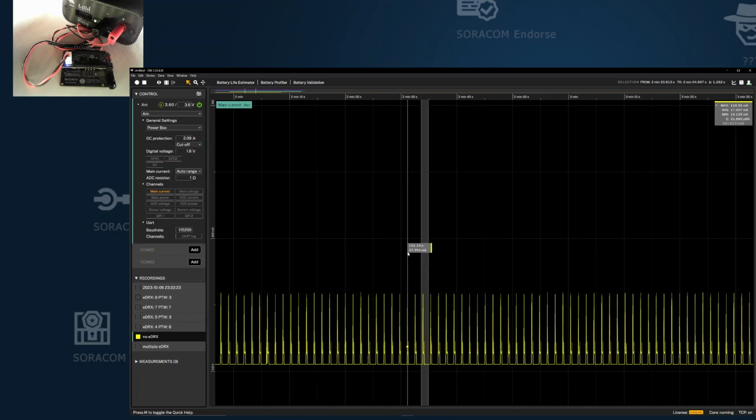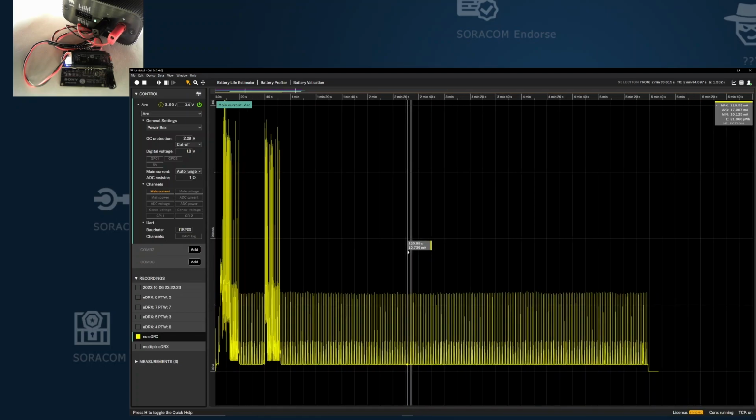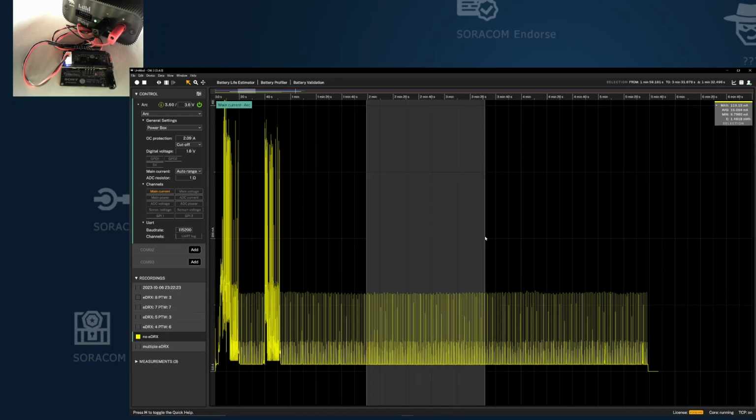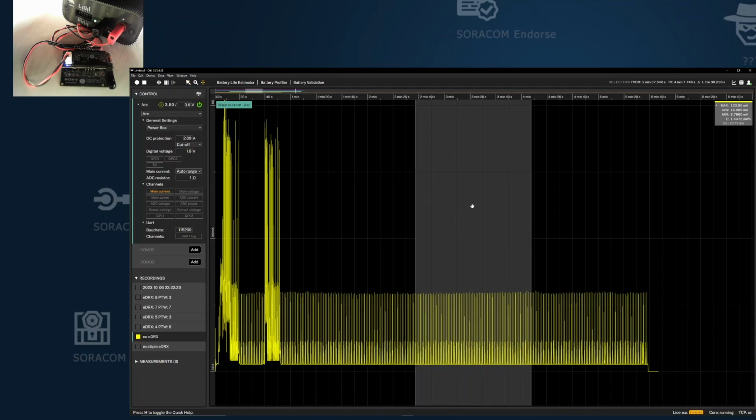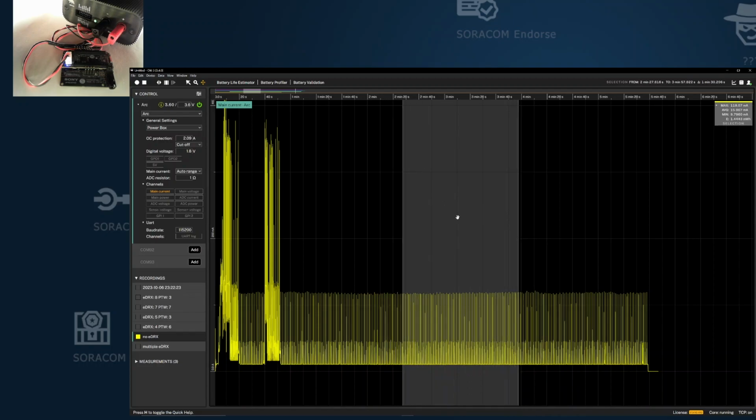and if I mark a sample time frame, let's take 1 minute and 30 seconds, for example. Within that 1 minute and 30 seconds, you can see in the upper right corner the energy consumption is 1.45 milliwatt hours. So we are even able to move this, and it's always around 1.4544 milliwatt hours.